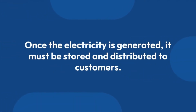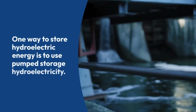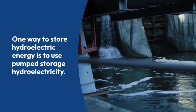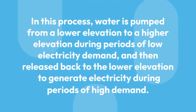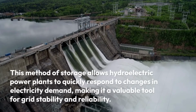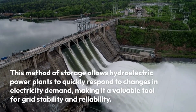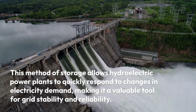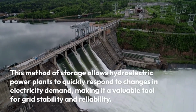Once the electricity is generated, it must be stored and distributed to customers. One way to store hydroelectric energy is to use pumped storage hydroelectricity. In this process, water is pumped from a lower elevation to a higher elevation during periods of low electricity demand, and then released back to the lower elevation to generate electricity during periods of high demand. This method of storage allows hydroelectric power plants to quickly respond to changes in electricity demand, making it a valuable tool for grid stability and reliability.